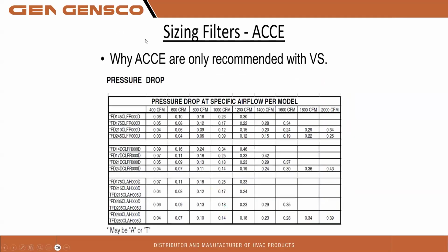So you start looking at our Clean Effects. Please only put Clean Effects on variable speed systems because the constant CFM blowers are designed for that. It's really hard to have a conversation with one of you guys over the phone that maybe that Clean Effects, as awesome a filter as it is, maybe it wasn't the right application.